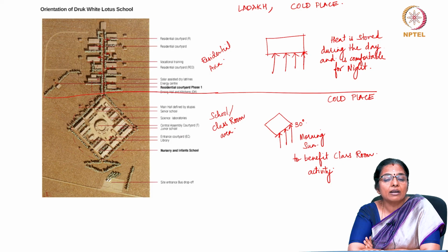The buildings have to be bulky and large. The spaces around buildings must not be porous. They must be compact so that there is mutual shading. Also, openings must be very few, otherwise they will bring in the hot air and also the sand dust, because hot dry regions normally are very dusty.